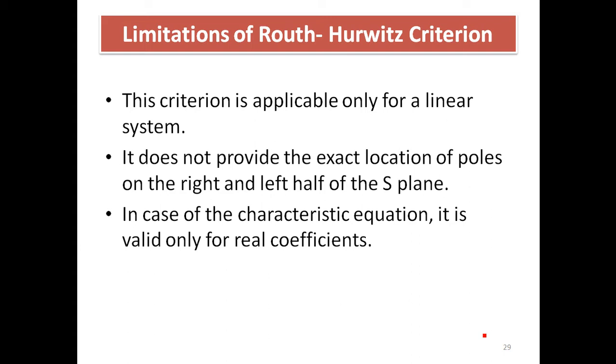But there are some limitations of the Routh-Hurwitz criterion. This criterion is applicable only for linear systems. Therefore, if you have e to the power minus st or any exponential term, you have to linearize that.